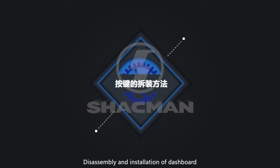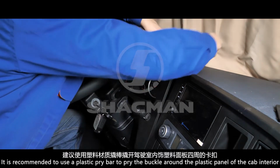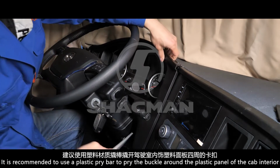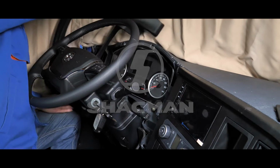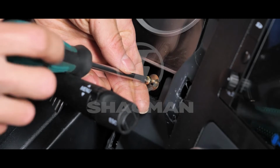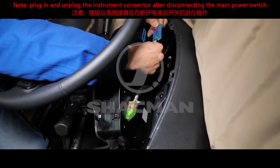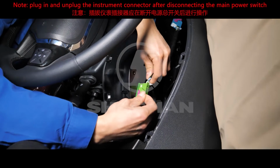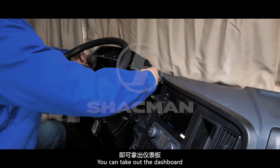Disassembly and installation of dashboard. It is recommended to use a plastic pry bar to pry the buckle around the plastic panel of the cab interior. Remove the bolts. Unplug the harness connector. Note: plug in and unplug the instrument connector after disconnecting the main power switch. You can take out the dashboard.